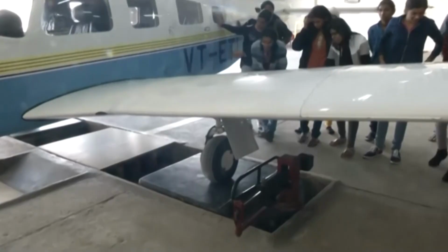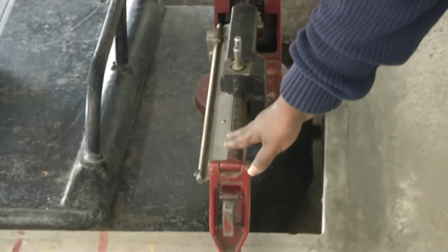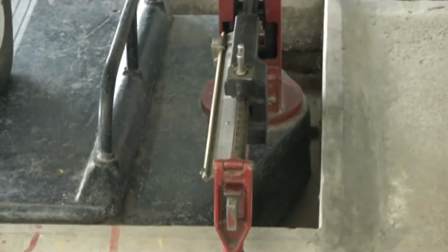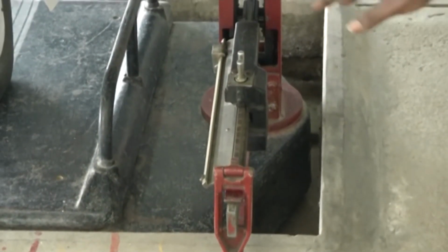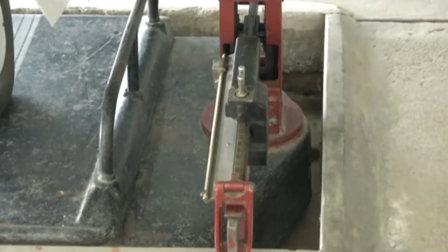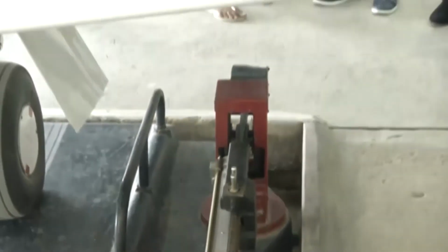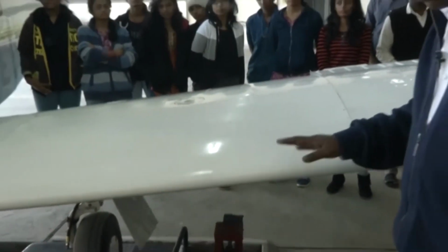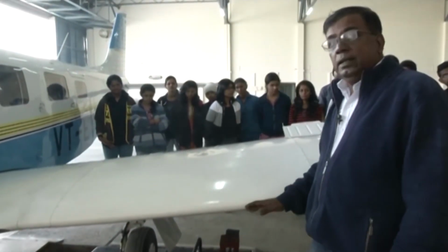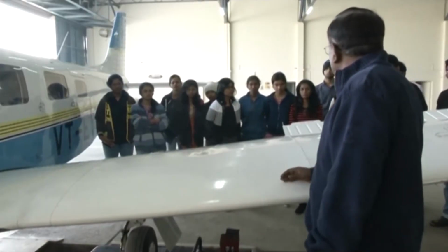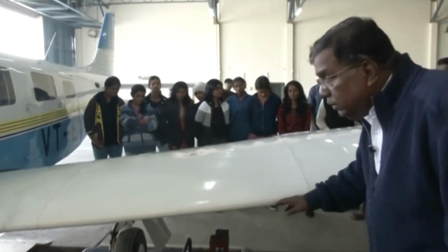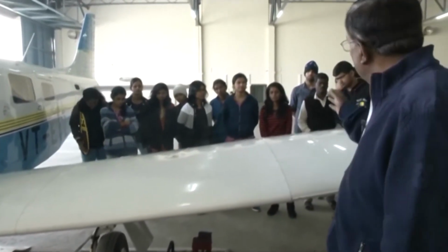Okay? Thank you. Now you see that these are the balances, one balance here, another that side, another at the nose landing gear. Now we have to somehow measure the reactions happening at these 3 balances. So how do I measure the weight or the reaction at these 3 points? Since we need to measure it by a scale, we need to know the least count of these scales. What is the least count of this scale? It's 200 grams, right? Now you will see how to measure the weight. Can you demonstrate how to take the weight?